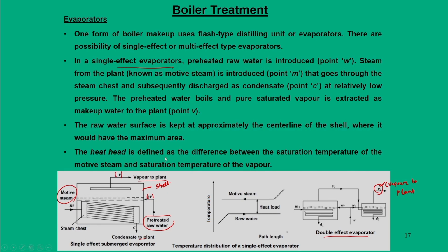We also define the heat head, which is the difference between the saturation temperature of the motive steam and the raw water temperature.